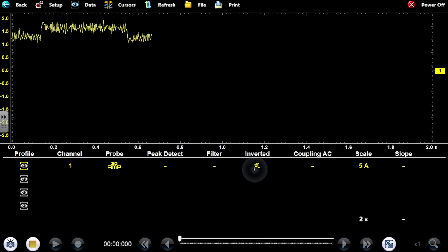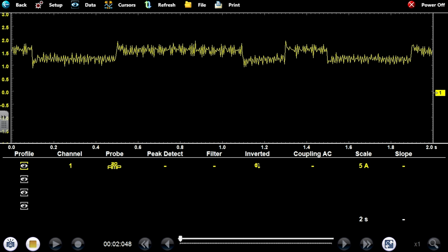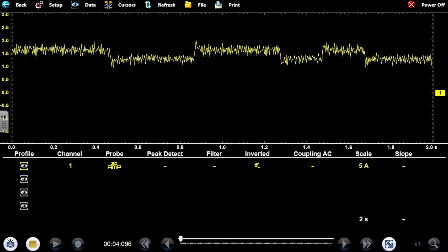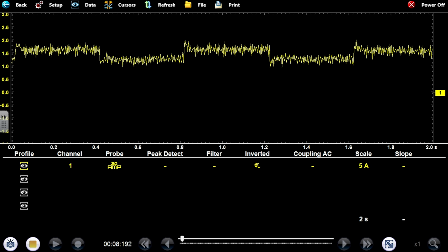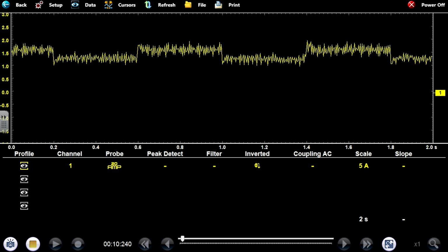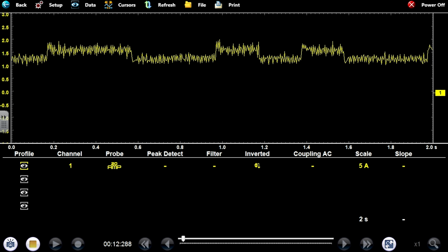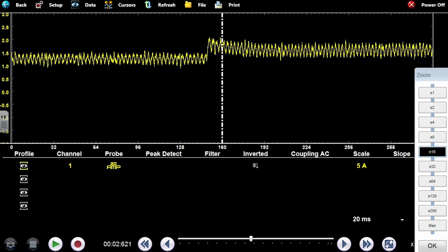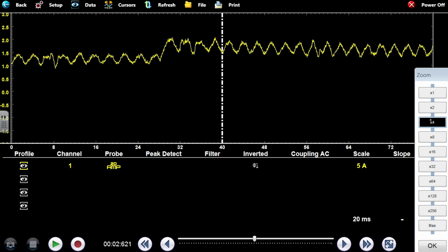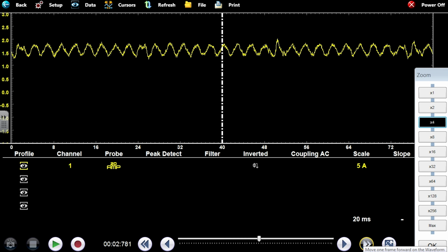Let's invert this. That is a super low amperage waveform, but again, this is a system that's controlling the pump speed to control pressure, and there's not a lot of fuel demand right now. It's not anything that would jump out at me. It's a much cleaner waveform than I anticipated. I don't see any dead armatures in this.